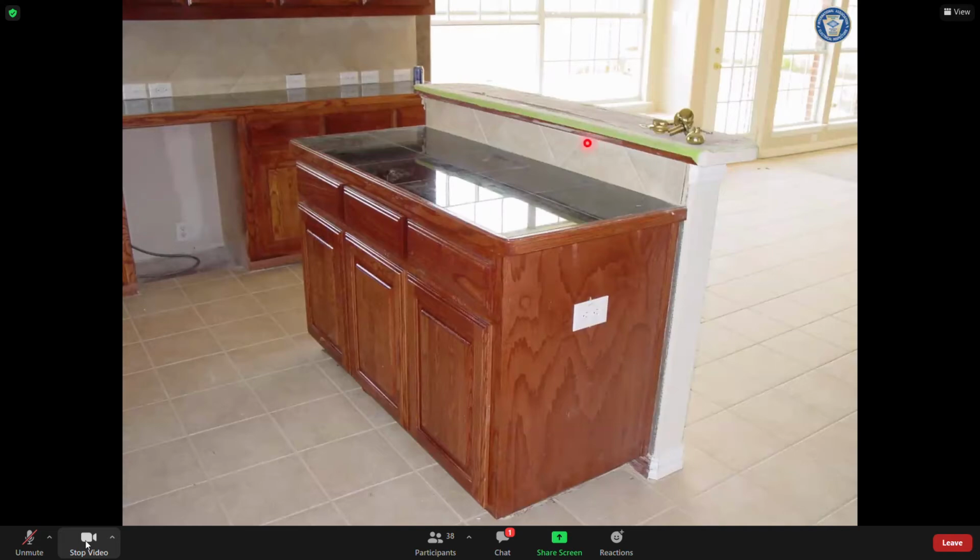This backsplash right here. Now under the 2017 code, 2018 IRC, the code tells me that there's only 2 provisions that will allow me to put a receptacle under a countertop or below a countertop and have that receptacle serve that countertop. And those 2 conditions are if the house is being built for someone that is physically impaired.